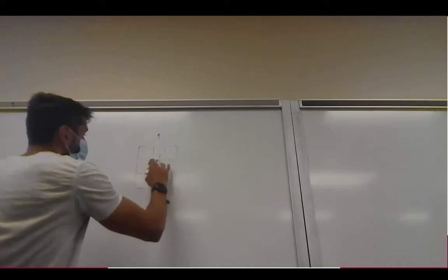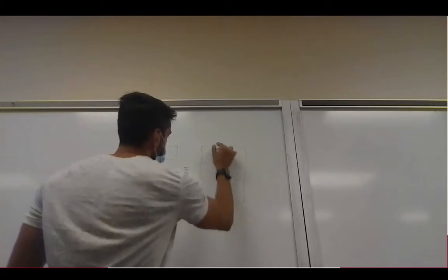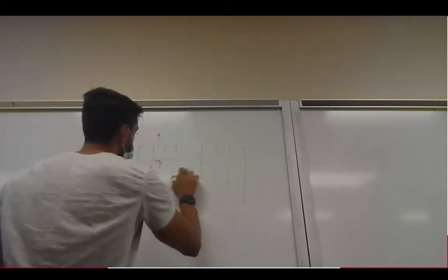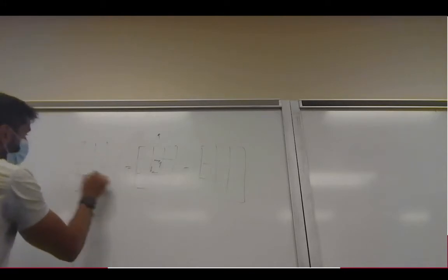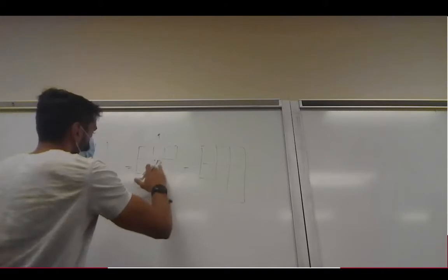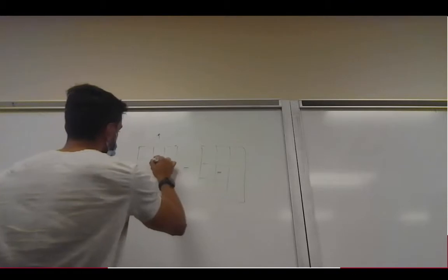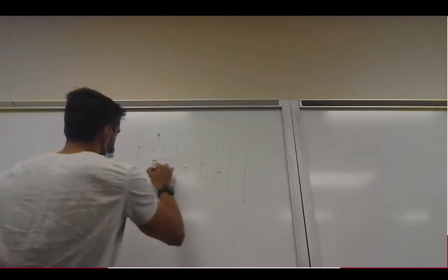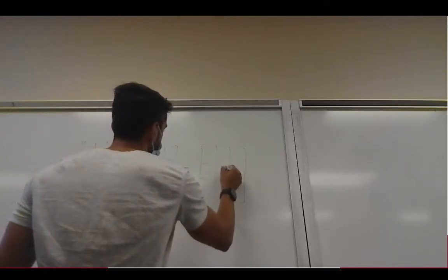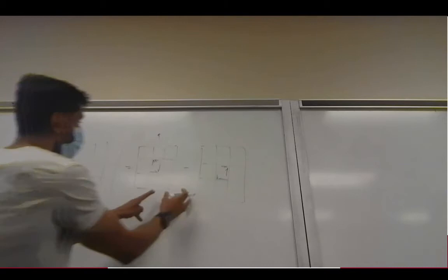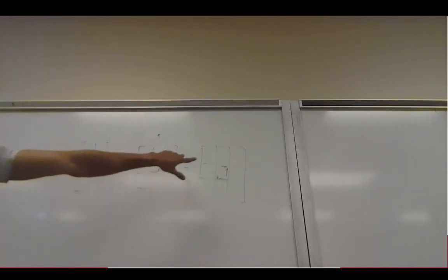So if we now remove this, what we basically can do is we can say, well, this is our pristine case where all the panels are existing. And we take whatever this panel is. If the shear flows are going in this direction, we basically add an opposite, equal shear flow to it. So when you add these two together, we get our panel width cutout. So they cancel each other in the middle section.